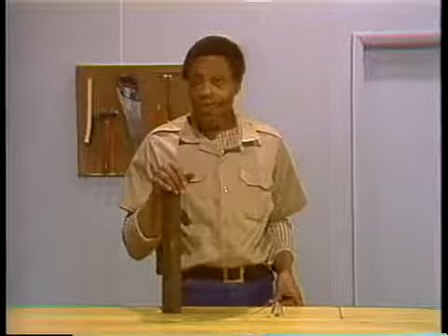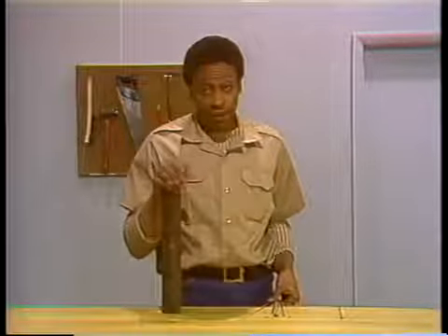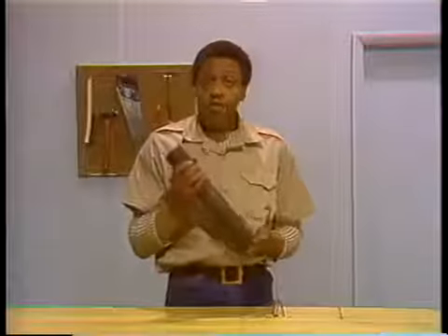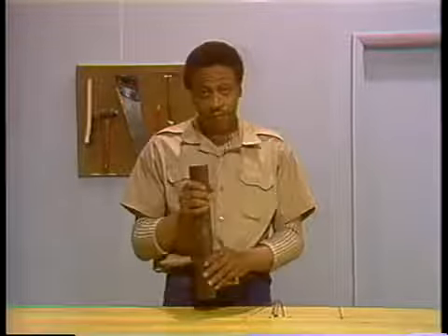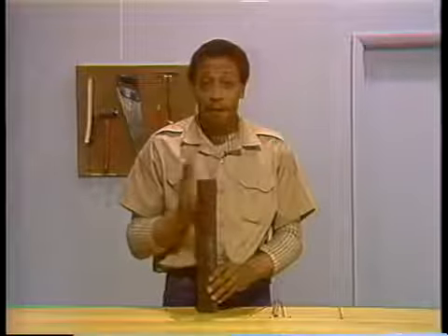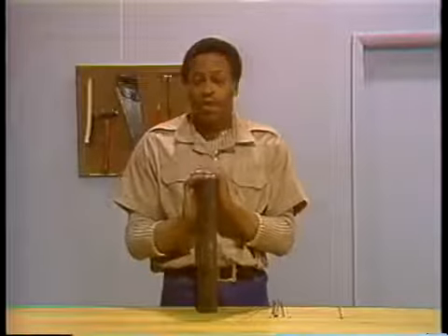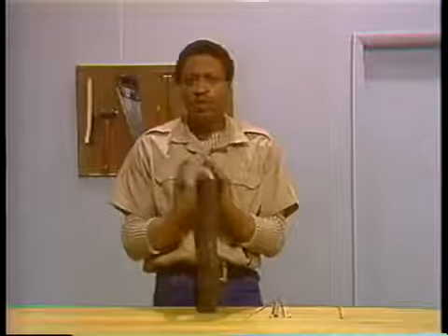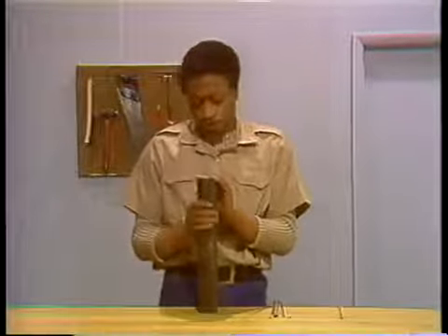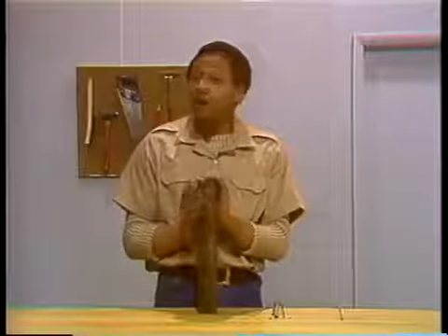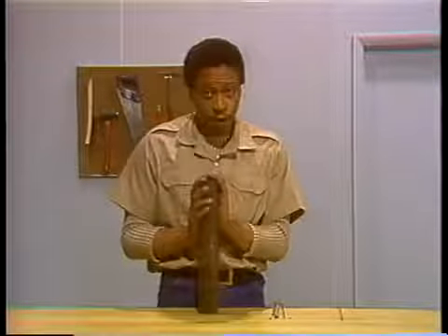In addition to the welding rod, you'll need a replacement tube. The new tube must be the same type of tube as the one that failed. It has to be made of the same type of metal, and its dimensions have to be identical. Your manufacturer's manual will tell you what metal the original boiler tubes are made of. Using the right replacement tube is very important.